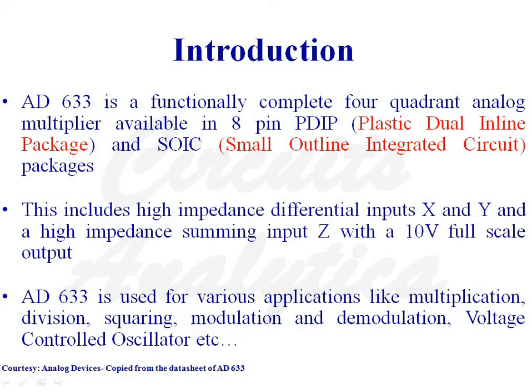AD633 is a functionally complete 4-quadrant analog multiplier available in 8-pin PDIP and SOC packages. This includes high impedance differential inputs X and Y and a high impedance summing input Z with a 10-volt full-scale output.